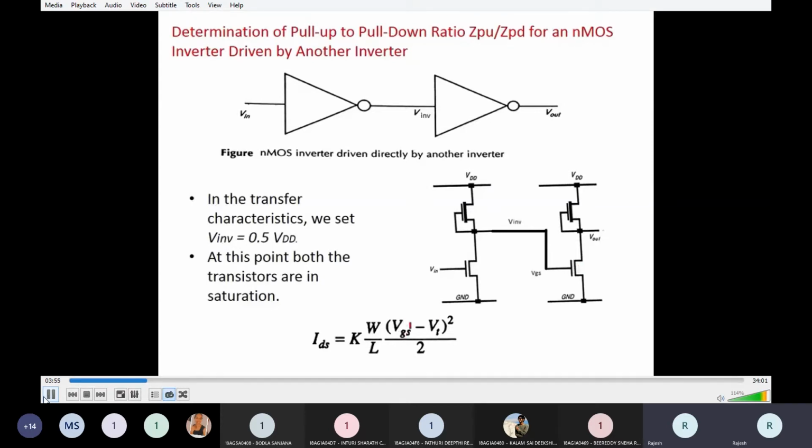So in this equation, the pull up network is the depletion mode MOSFET, so we are calling it the pull up network. Why? Because whenever this MOSFET is on, VDD is connected to output, hence we will get high output. So this pull up network always tries to make the output high, that is, it always pulls up the output. Whenever this pull down network, the NMOS transistor, becomes on, output is connected to ground, hence output goes to 0. So whenever it becomes on, it tries to pull down the output to 0. That's why it is called the pull down network.